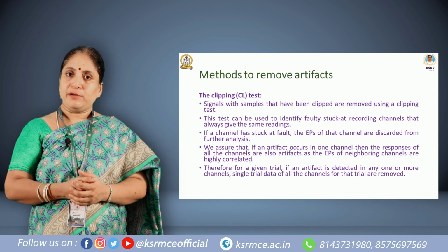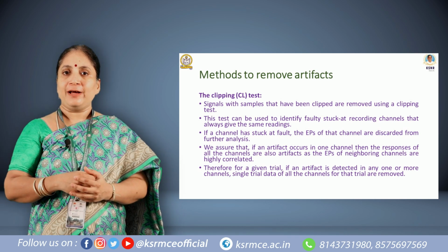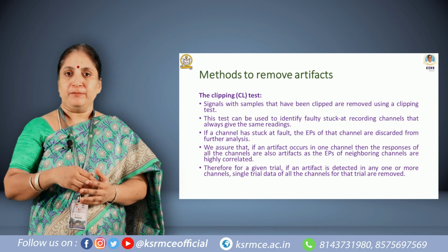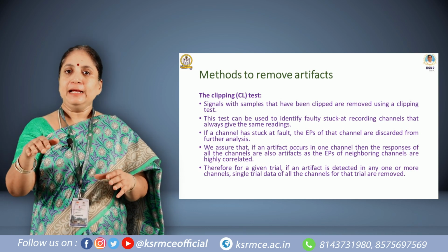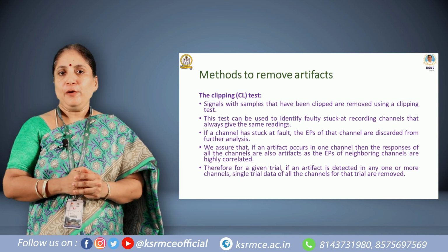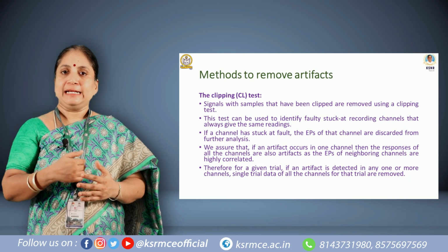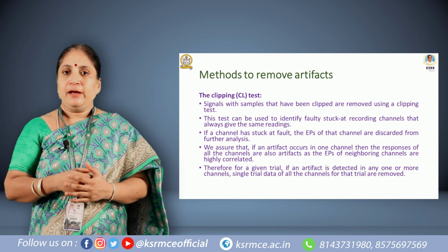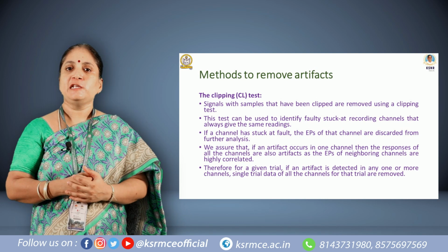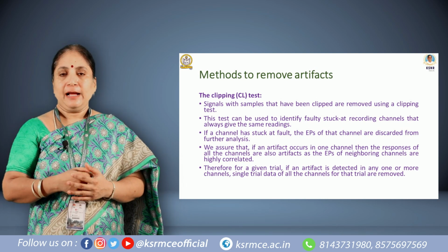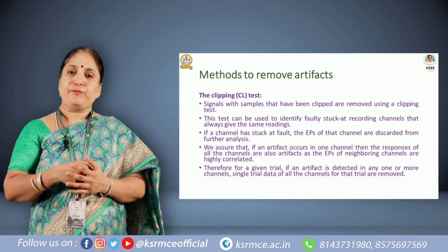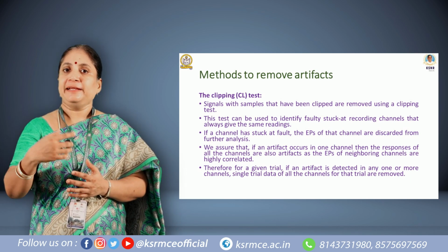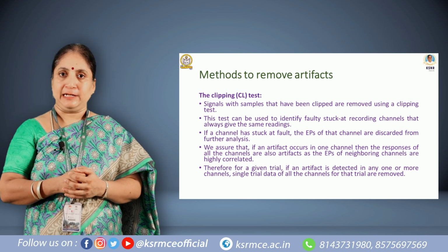In such a case, the waveform morphology will be observed as a clipped waveform. So, by identifying the signals which are clipped, we can identify the channels with stuck-at fault. And if there is a channel with a stuck-at fault, there is a higher probability that the nearby channels also have stuck-at faults.